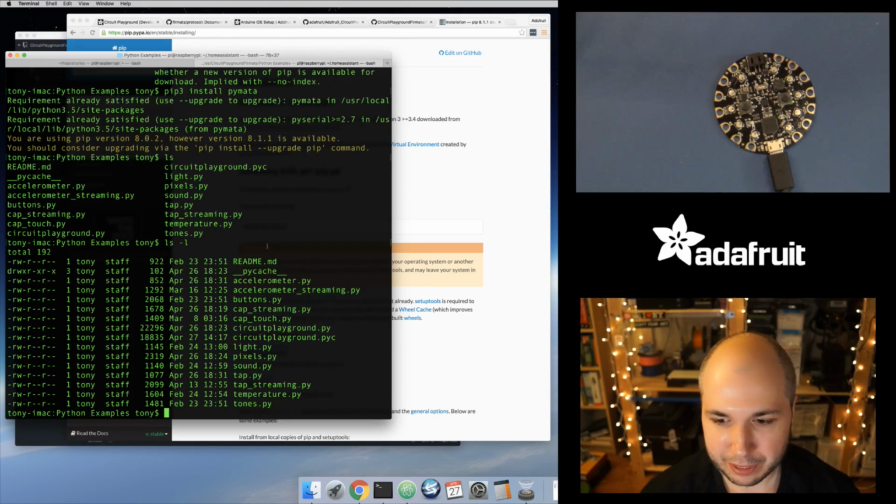So let's dive in and see what we can do. Let's play some of these demos. I want to start with the buttons.py because that's a real simple one of just pressing the buttons. To run all of these demos, you want to run Python, and I'm going to use Python 3, and then you have to give it a command line parameter that's the name of your serial port that the Circuit Playground is connected to.